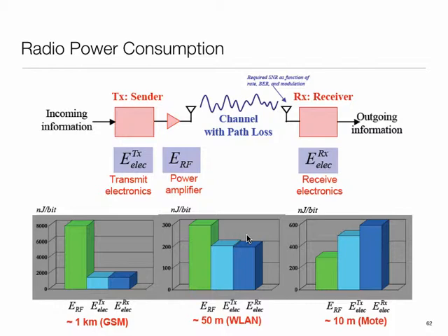Or now 1 gig level is the AC, 802.11ac can go all the way to a gig. Point is, it's much higher. So I expect the electronics might be more power consuming, possibly because it has more sophisticated algorithms operating at a higher rate, but my amplifier power is going to be lower.